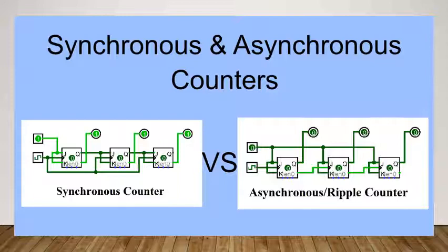So these are designed using flip-flops and JK flip-flops are generally used. And we can see here J and K both are shorted. So either both J and K become 0 together or they become 1 together. And the changes in the output will be as per the truth table of the JK flip-flop. Now, in the second counter also you can see JK flip-flop is used, J and K inputs are shorted, and we are taking the output from each flip-flop to represent the count.